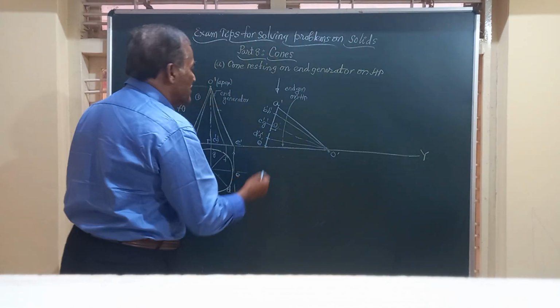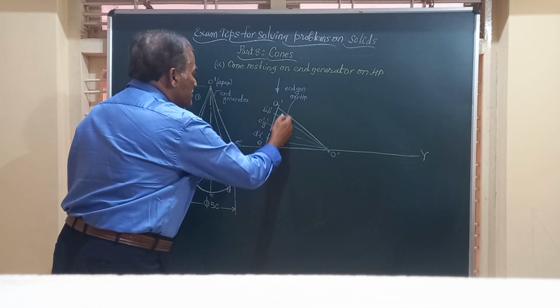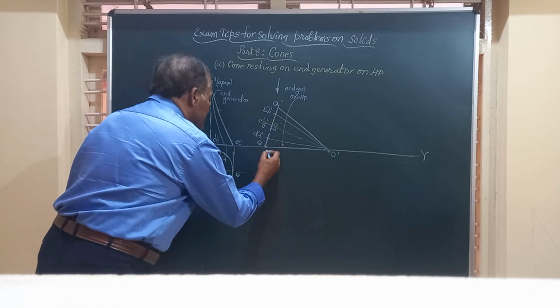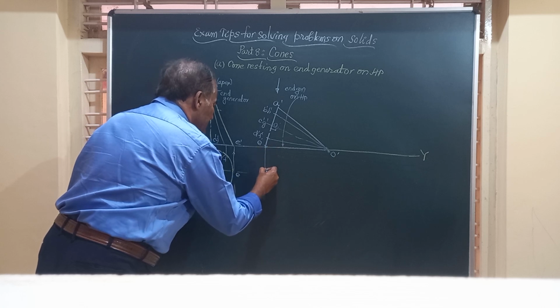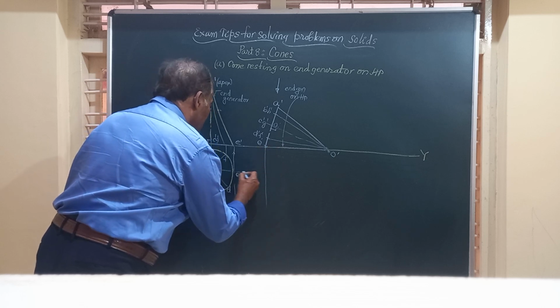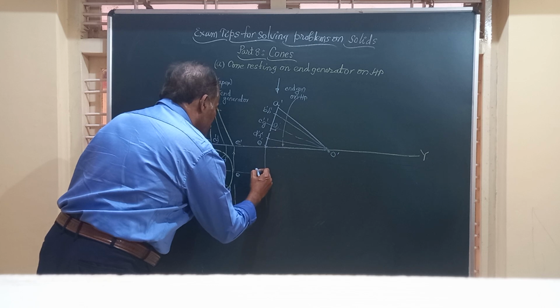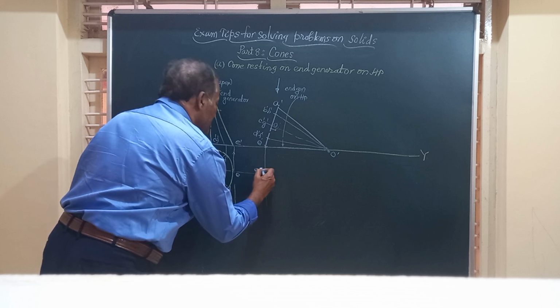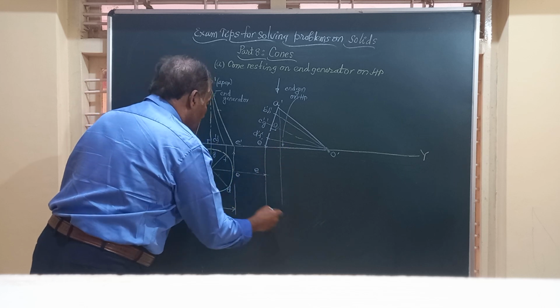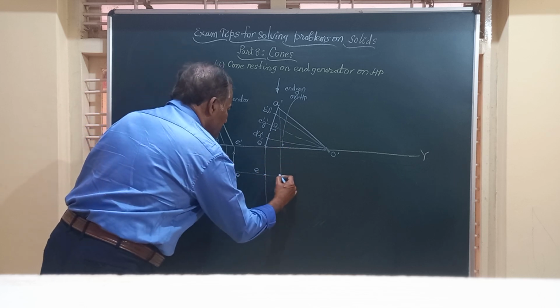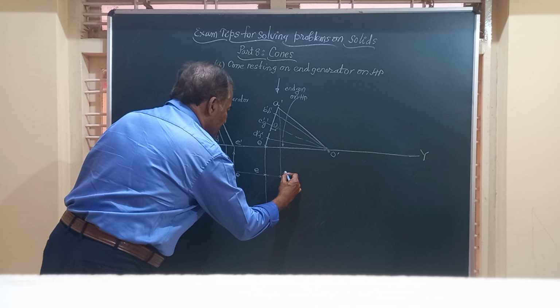And hence, friends, I am going to obtain all these 8 points of the base, and let's see how it looks in the top view. So draw a vertical line from here, a horizontal from here. This is our point, say E. Similarly, vertical line from here, horizontal line from here. You are going to get this point A.